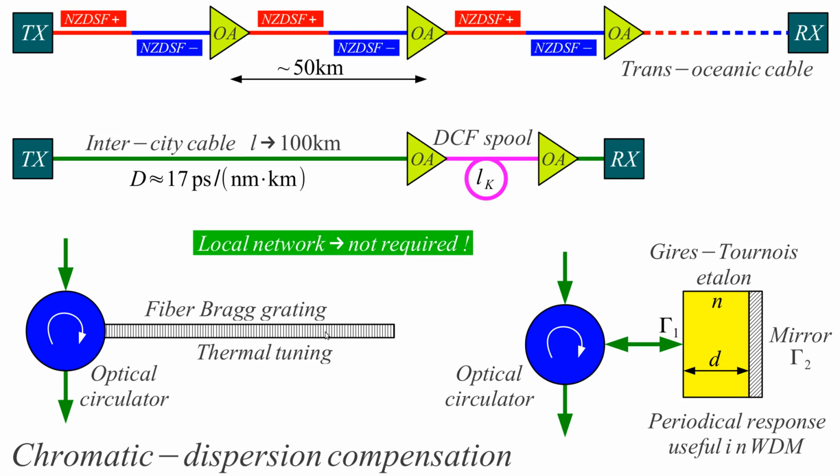When ultraviolet light hits germanium inside an optical fiber, it slightly changes the refraction index of the glass. So with ultraviolet light we can write whole gratings using interference patterns.